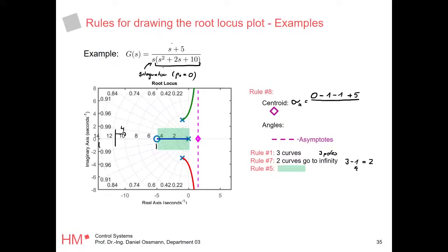The zero is at -5, so it turns positive. And now we've got 3 - 1. And here you see the first time that our centroid is in the right half plane, right? It's plus 1.5. So why does that actually matter? Well, let me get to this in a second.